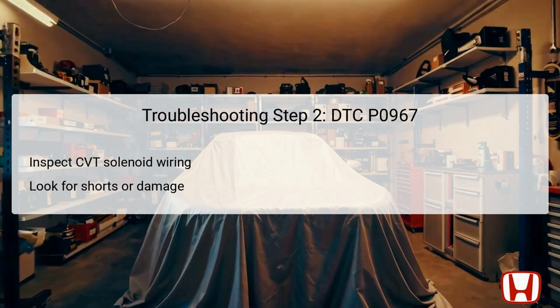If a short circuit is detected in the wiring, it may cause erroneous signals to be sent to the TCM, triggering the DTC. Proactively identifying and rectifying wiring issues can significantly improve the likelihood of solving the underlying problem affecting the CVT system.